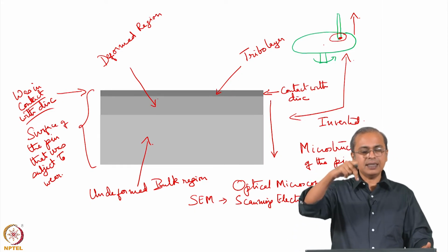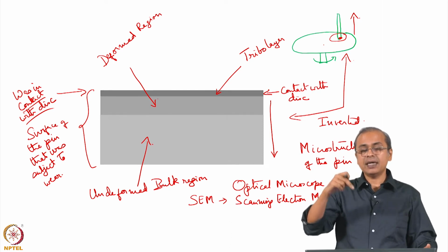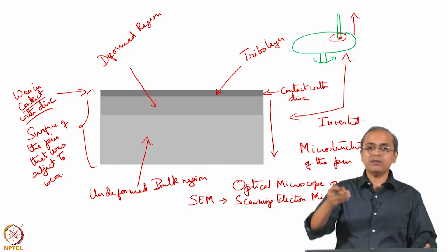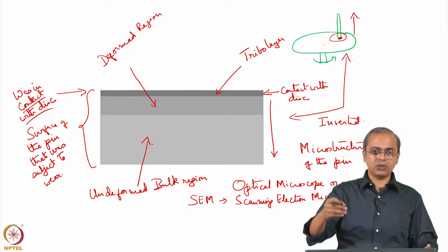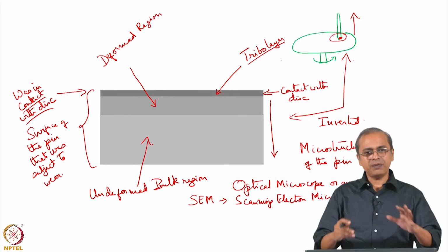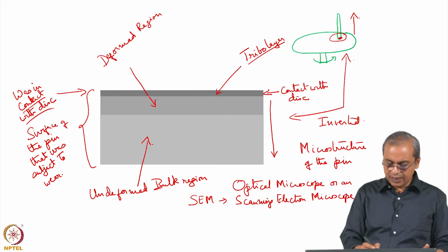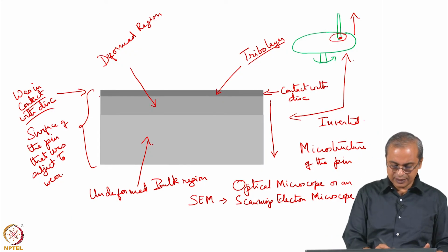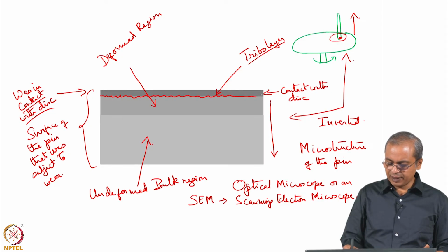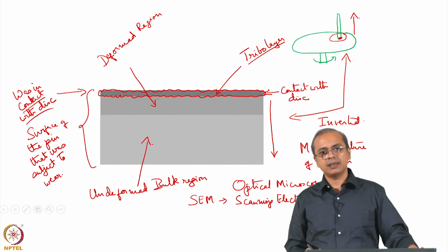The layer that is directly in contact, any kind of oxide layer it has, that oxide layer gets damaged, and then whatever is the exposed layer, that also gets oxidized. So you usually have sort of a damaged debris-like layer which sits on the top. Even though I have shown it in this schematic as some kind of uniform layer, actually it will be a rough, somewhat damaged and uneven layer that you will see out here, and that is your tribo layer. This is called tribo layer.